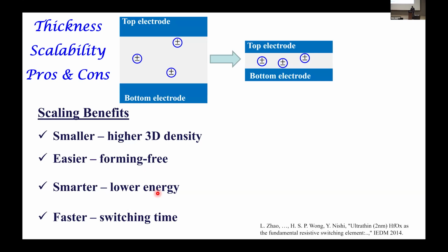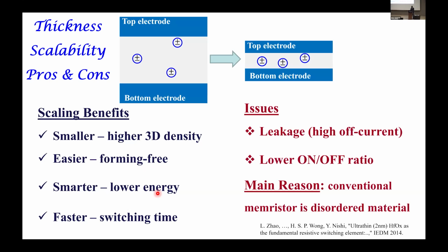However, we also know in semiconductors that there's no free lunch, which is the NFL policy. There's always going to be some challenges, otherwise there's no need to do research. Some of the challenges are that when you make these sandwiches smaller, you can get uncontrolled leakage phenomena, current just flowing. So you lose this on-off ratio, you lose this ability to cycle this.